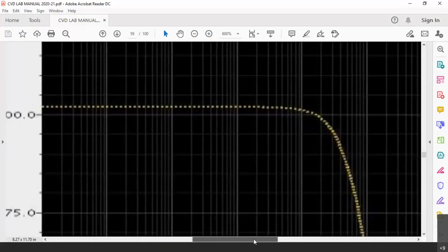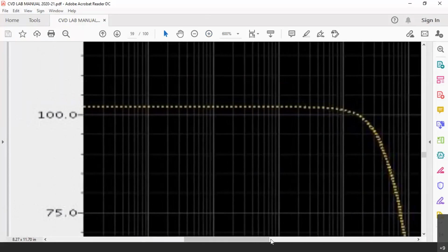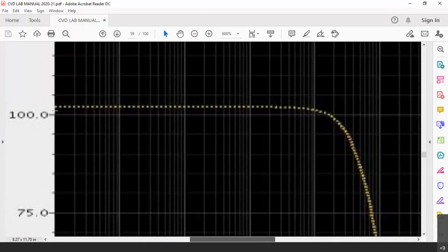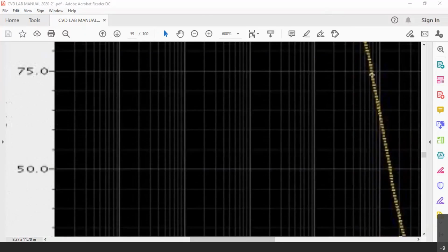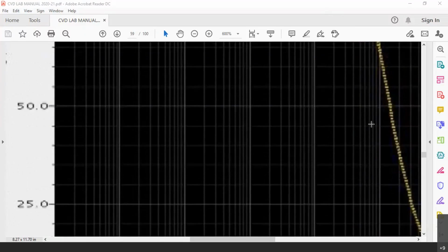Now the gain is 100, let us say, or 40 dB. Now from 100, we have to come down to 0.7 of 100. That means we have to come down to 70. Let me take it as approximately this point, because anyhow it is slightly more than 100 here. So let me take it as this point only, approximately. Now when we take that point, go down from that point. From this 75, let us go down.